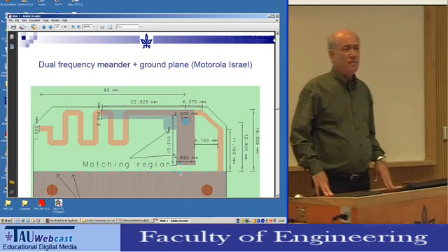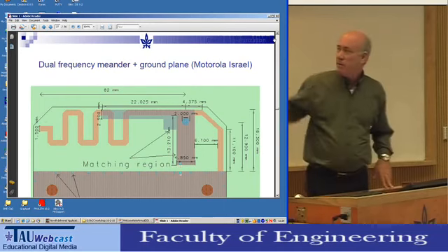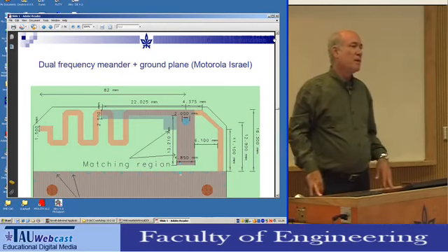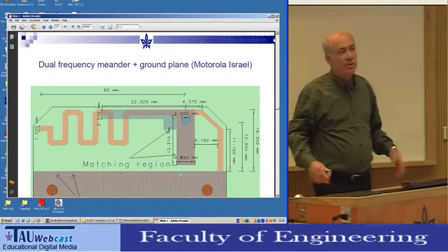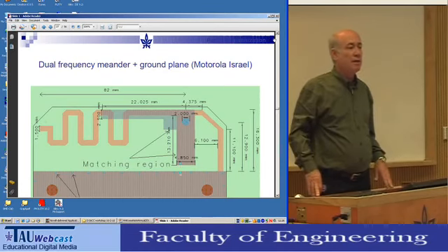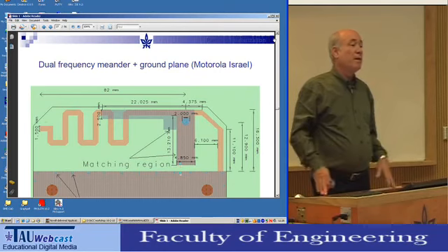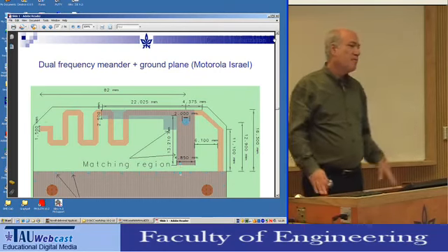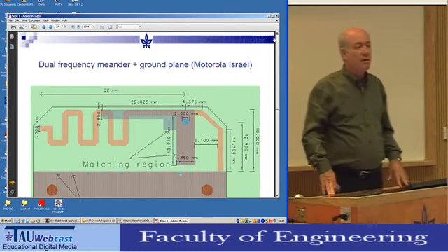What about ferrites? You can add ferrites? People are using ferrites, yeah. The list of materials that I showed before also included ferrites. So ferrites are a good idea. They are just non-reciprocal and they are heavy and things like that, but people use ferrites. Part of the idea is that you either increase the epsilon or increase the mu. Ferrites increase the mu, but not in an isotropic way.